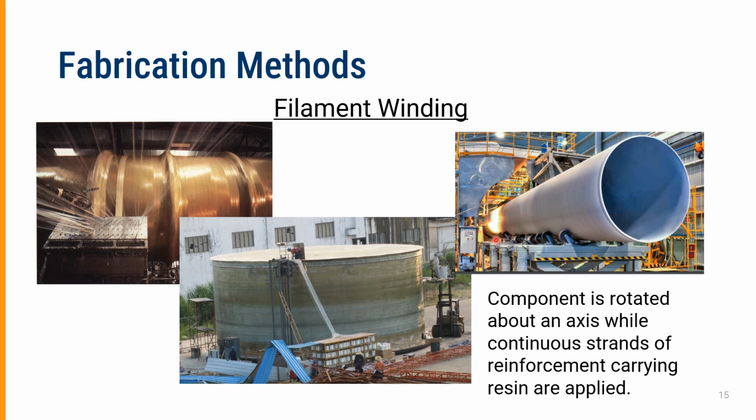And this is an example of a continuous winding operation where the mold actually moves and translates the pipe in the axial direction. So the pipe is rotating and translating in this direction so that all of the materials are applied in one place. And by the time it gets past this area that's lighted, it's basically cured and ready to go.